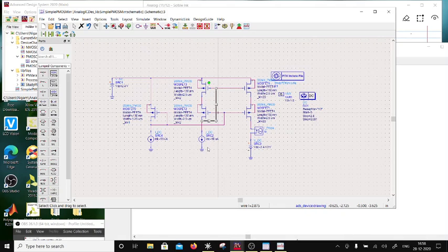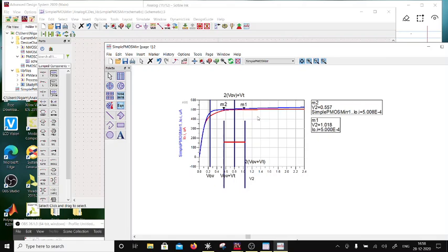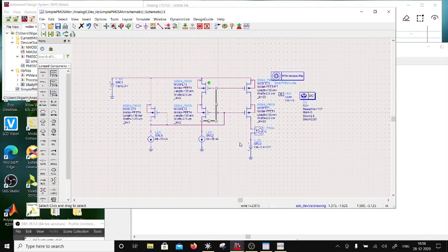Okay, so we have covered 3 or 4 variations, and the idea was to improve the output resistance so that the output current is a ratio 1:10 or whatever is the mirror ratio for a large range of output voltage. So that was the whole goal. Now once you have that, we can start using this as a load for your gain stages. So I'm going to stop here for now, right? And maybe I'll cover gain stages in the next session.